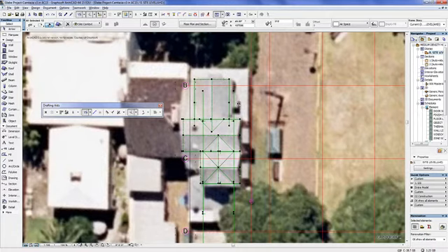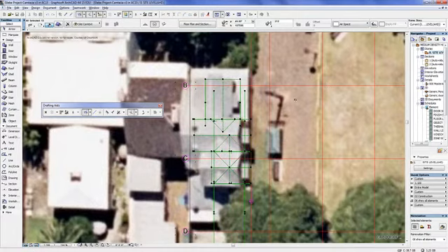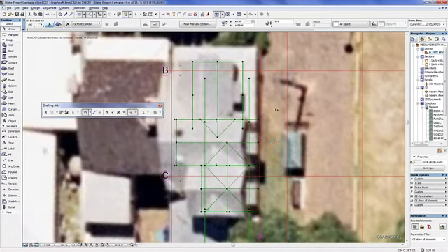Okay, so I've got quite a few roof planes, so I'm just going to go Control D. I'm just going to move this to here, okay, because that's technically where it is footprinted on site. Well, actually, technically, it's probably a little bit back from the boundary line. Okay, it's probably like that. All right, so this is just ignoring the skew on the side.